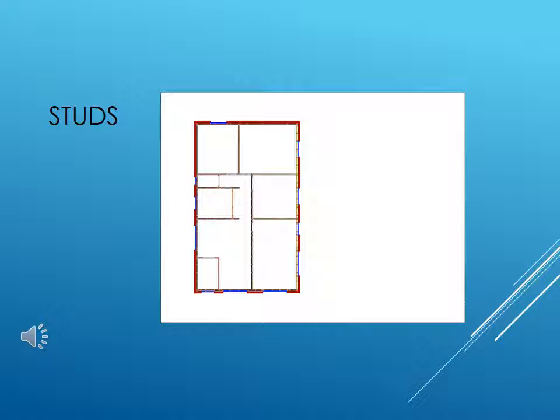Okay, at this stage, when you look at this drawing, the scale is very small, but you can increase it in size, and you'll be able to tell where the studs are. Why are we using studs more than one either side of a window? That's all to do with lintel load and also wind load. And when we get into wall frames, that will be actually made more clear to you.